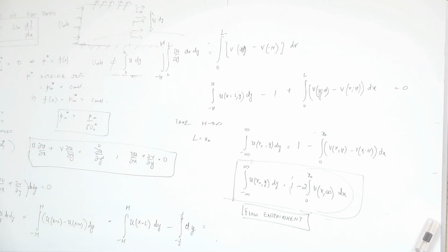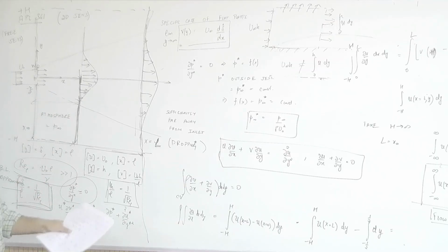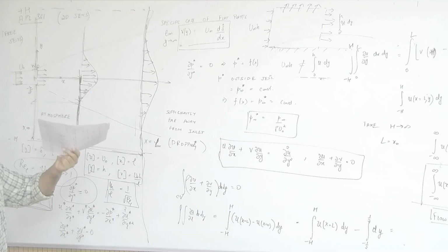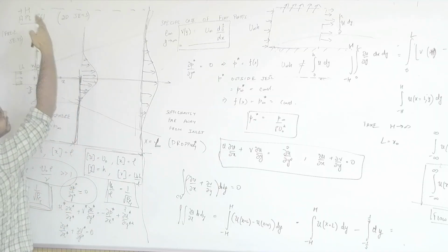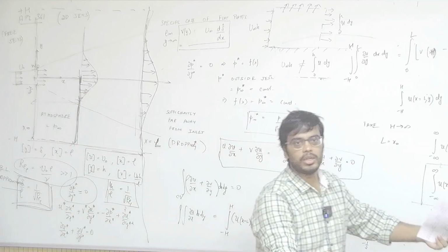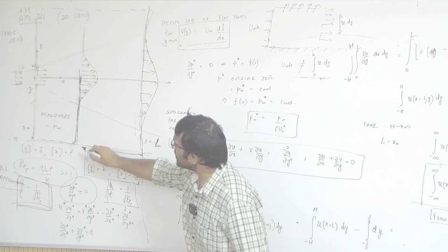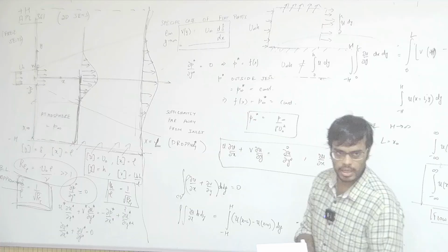Flow of some velocity coming out is going to accelerate the flow in its boundaries at other y locations. What it does is it basically sucks in the other fluid, the outside atmospheric fluid, also into the jet. So there is an overall entrainment inside this jet, and we are going to derive what this entrainment is equal to.